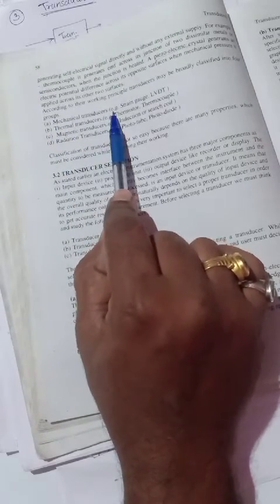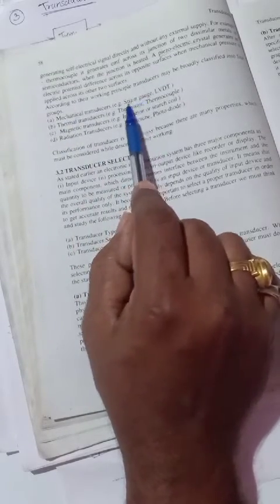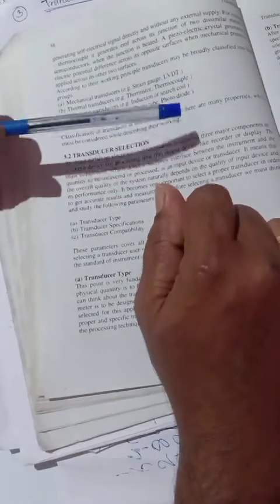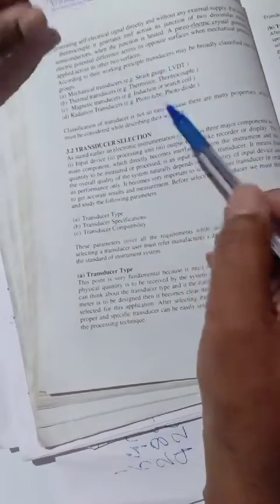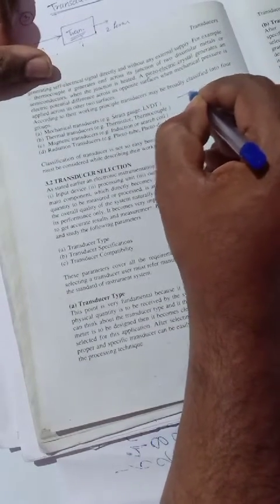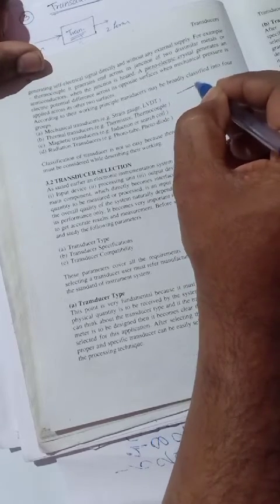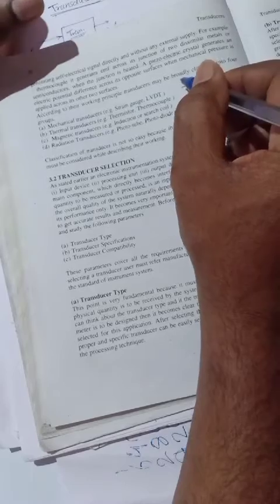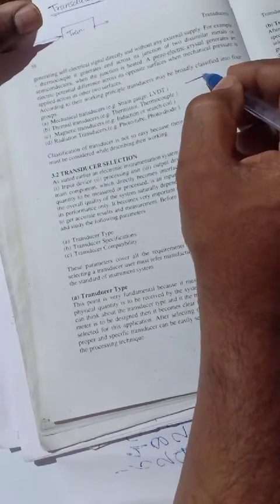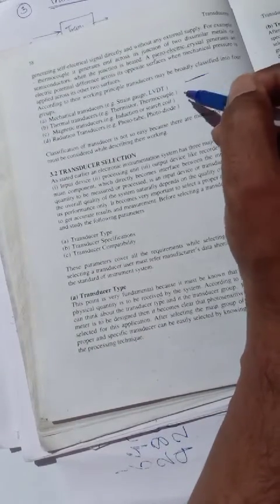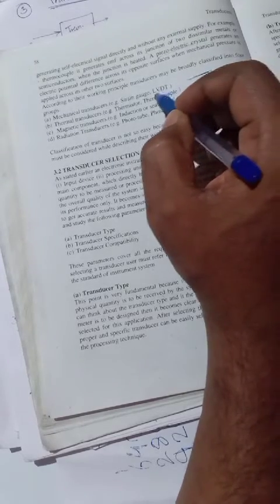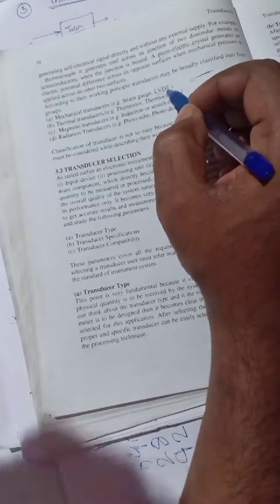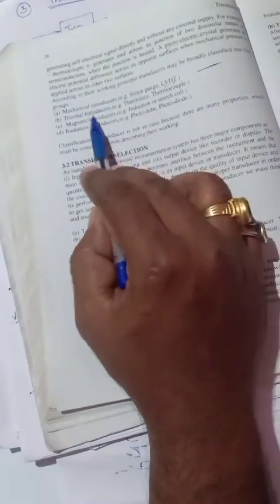That is the mechanical transducer, where there are some mechanical movements. For example, a strain gauge is a long, stretchable wire. If we stretch this wire, its internal resistance changes because of the change in cross-sectional area, and this change is used. That means this wire converts pressure into a change in an electrical signal. So this is a mechanical quantity. Another is the LVDT, linear variable differential transformer, which also responds to mechanical changes. So this is a mechanical transducer.